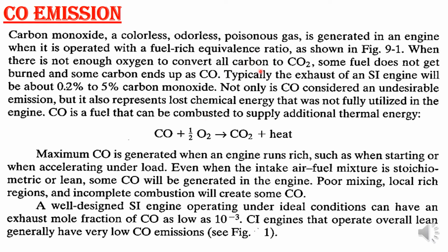So first we will have carbon C plus O2, which gives CO plus O. That CO will react with the O2 and give CO2 plus heat. So this is the process for complete combustion of the fuel, but in incomplete combustion maximum CO will be there. The percentage of CO increases in the idle range as well as at lower load, because it will operate in a richer region. The passenger car CO percentage has been found as high as 7% with a rich mixture and 1.25% near stoichiometric.